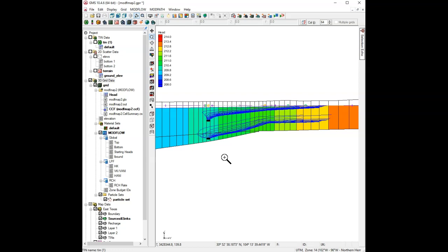Now, by the way, there is a way to more explicitly delineate how those particles are distributed along the well screen. You can have greater control over that, and we'll talk about that a little later. But anyway, that's what we're looking at when we're looking in plan view. This is kind of a 3D view. This also shows these path lines are three-dimensional. I mean, they have an X, Y, and a Z component, so it's not just 2D. So that works out really well.